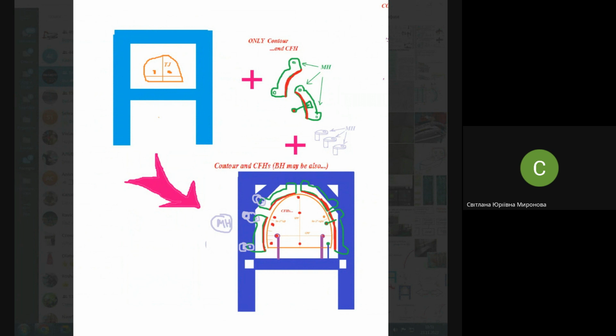In order to inspect the jig, for instance, or to repair the jig, you need to understand exactly where the first position of the template was. For this, you make special locators, which are literally reference holes for locating the template again back to the same position in the jig. They are not in use during the jig life. We may mention them separately as elements in the diagram of coordination. Right now, we do not talk about them, and we may pretend that they are hidden in the diagram of coordination, like coordinate fixing holes, because literally it's the same thing.